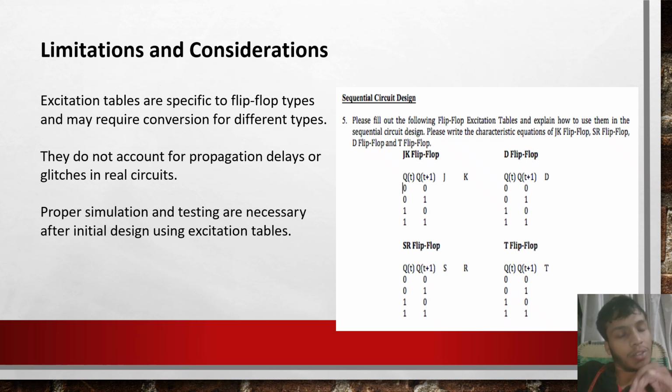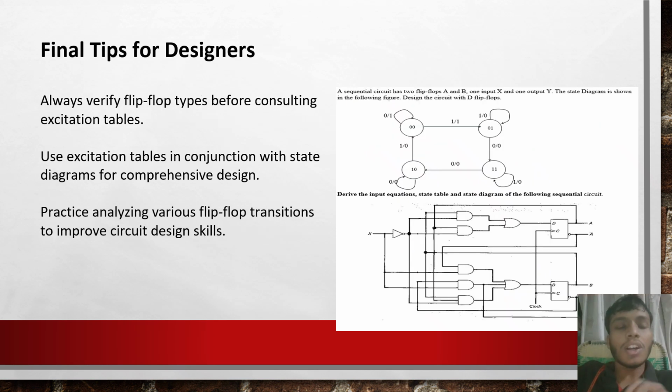Limitations and considerations. Excitation tables are specific to flip-flop types and may require conversion between different types. They do not account for propagation delays or glitches in real circuits. Proper simulation and testing are necessary after initial design using excitation tables.